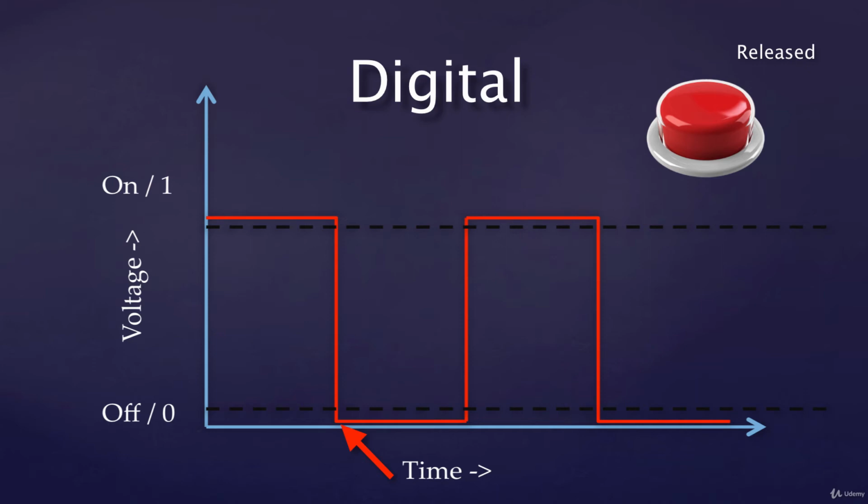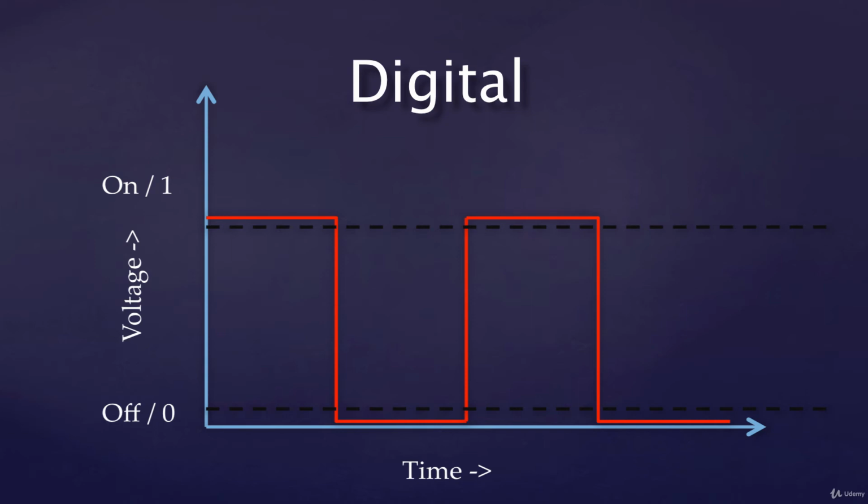In digital electronics, when a voltage is above a certain threshold, in this case it's 5 volts, when it's pretty much there at 4.7 it becomes high. And when it's low, this is recognized when the voltage is below 0.3 volts. Don't worry about the particular voltages, we cover this in our examples, but it's just handy knowledge to know.